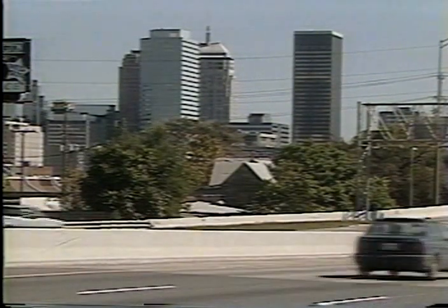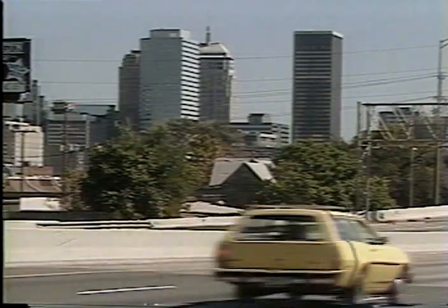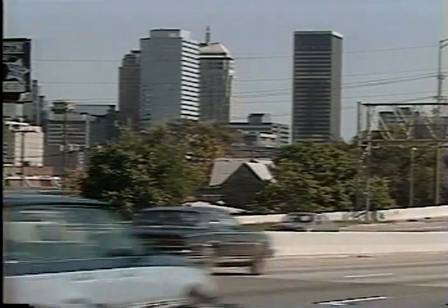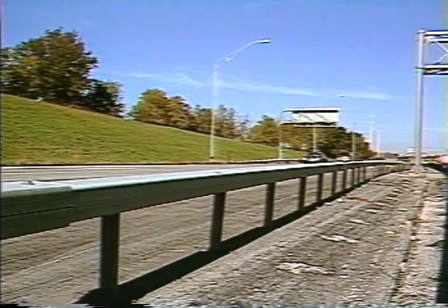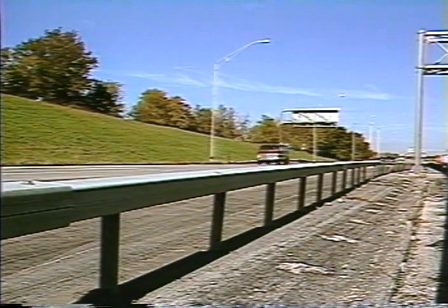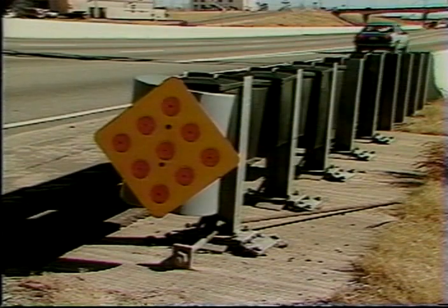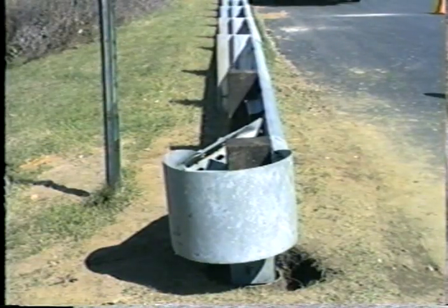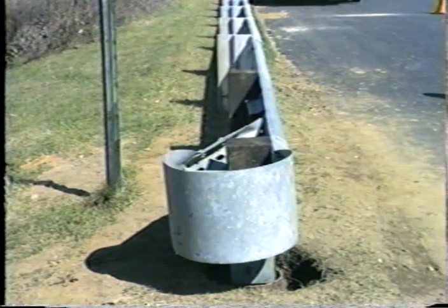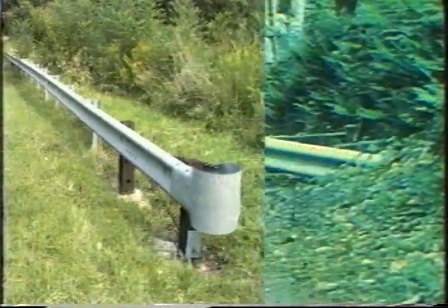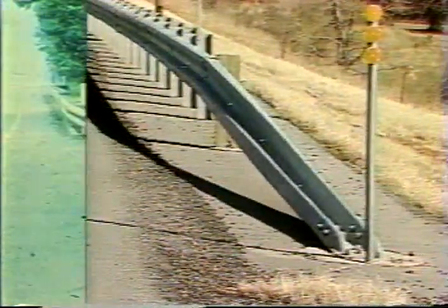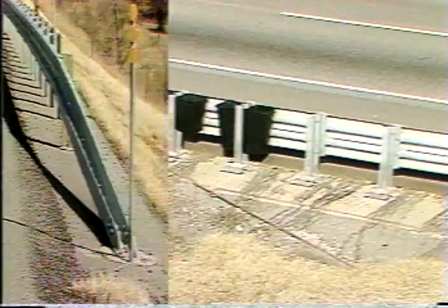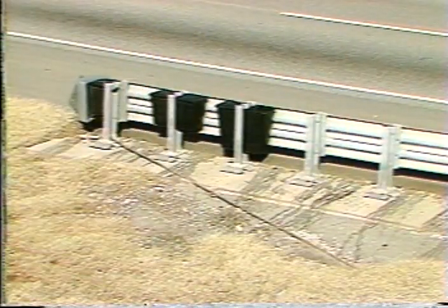Traffic barrier safety systems, whether they be roadside barriers, median barriers, or bridge rails, all need an end treatment. It makes no difference what type of barrier is involved. It can be flexible, semi-flexible, or rigid. All must have some form of end treatment. In this program, we'll look in some depth at 4 end treatments: the breakaway cable terminal, the flared and buried, the twisted and turned down, and the sentry end treatments.